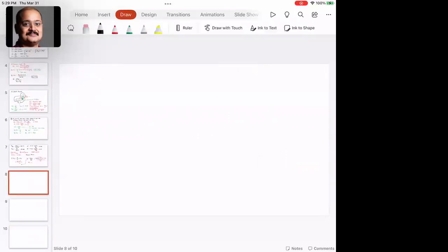So next step, WT is equal to sigma naught times y prime times b times pi times m times L minus b by L. Now here, I just want to give you something to think about. This is the actual process. So what you will do is, you will go to the table. For steel, you would find out the value of sigma naught. You know the value of y prime, and then you can substitute everything else and find out the module.